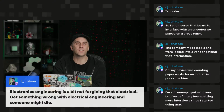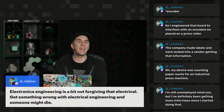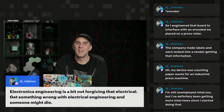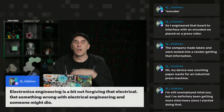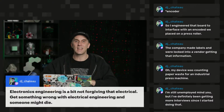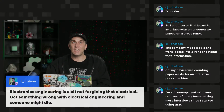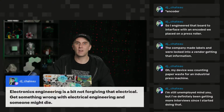You just can't short things. And there are a lot of conditions from which you can make very serious mistakes and still recover. You would be amazed at the kind of things that electrical engineers do to fix their mistakes in small batches and small runs. That includes forgetting to ground a trace and having to scratch a little hole and connect each one to ground. These sorts of mistakes can kill a design, but then allow it to be revived with an appropriate amount of fixing work.